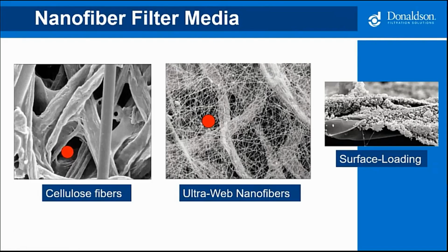So submicron, where is the air going to go? It's going to find its way through this cellulose filtration media, and it's going to find these avenues, and it's going to go deep. And then it's going to lodge in against the cellulose, and then we're going to reverse pulse it, and it's going to hopefully pulse off. But when this dust gets so deep on us, our differential pressure goes up. It remains up because when we pulse, it doesn't clean as efficiently as a nanofiber.